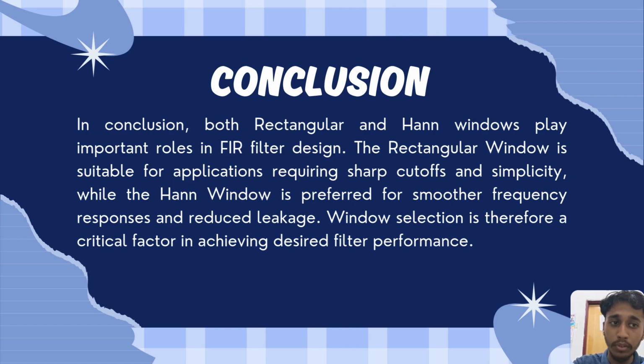But if we are looking for a smoother result where we need to reduce unwanted signal like noise and leakage, then the Hann window is definitely the one we have to choose. At the end of the day, picking the right window is the secret to making sure our filter actually performs the way we want it to.